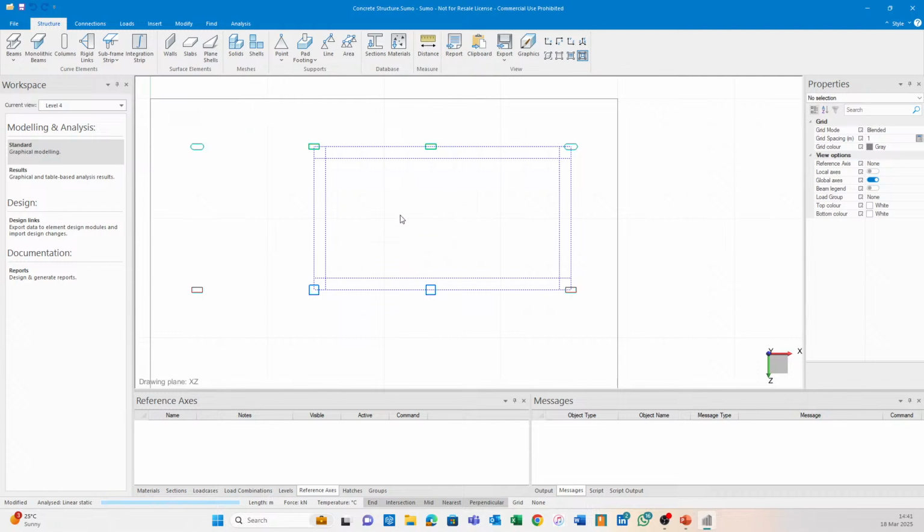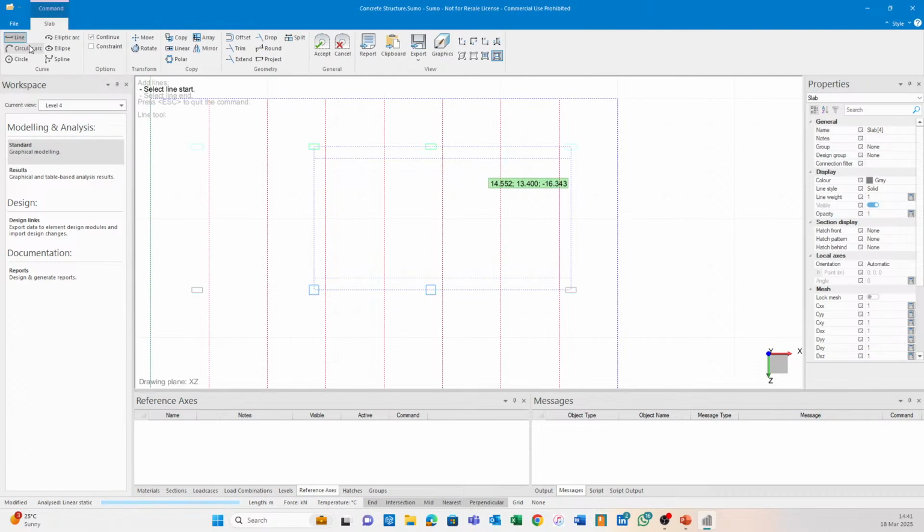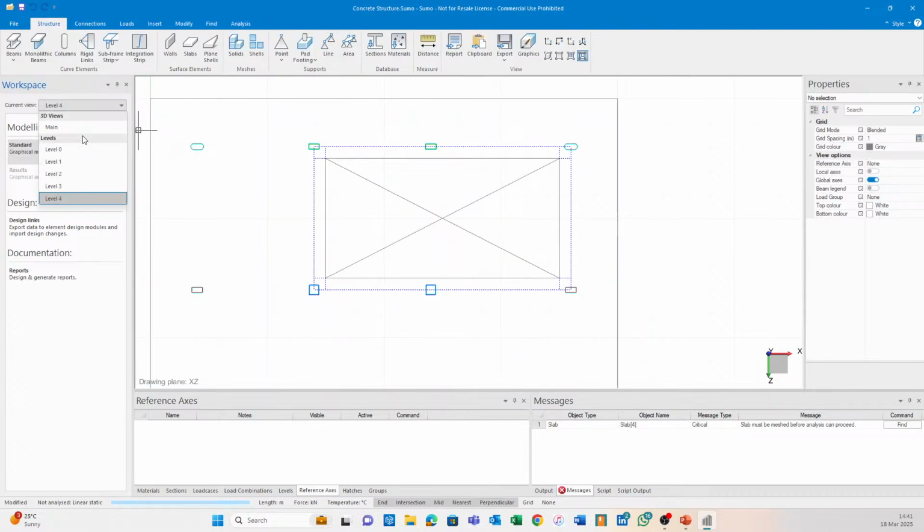Okay, cool. We've got that. I'm going to select the slab, click modify. That's good. It's continuous. And I'm going to select these sections over here. All right, and we've got our cutout.